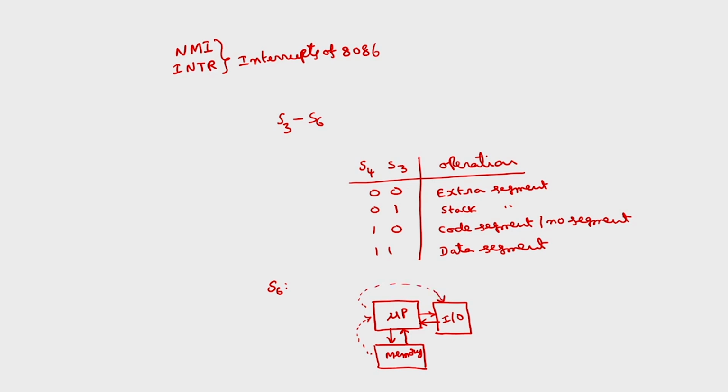This is the normal conventional data transfer scheme. Whereas this is time consuming, so for that we can use direct memory access between the memory and IO. This is called DMA, direct memory access. But in order to perform this DMA operation, the microprocessor requires the control of the microprocessor buses. For that, the memory will request the buses of the microprocessor through the hold signal, and the microprocessor will acknowledge with hold acknowledge, HLDA, and transfer the control.